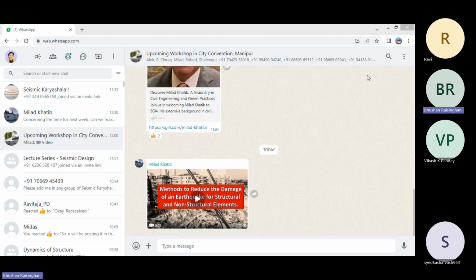The spacing should not be more than 1/3 of the minimum member dimension of the boundary element, that is the width. The thickness of the wall will be the minimum in this particular case if it is a rectangle. So 1/3 of the minimum member dimension of the boundary element, which will be thickness B or T, or 6 times the diameter of the smallest longitudinal reinforcement bar.